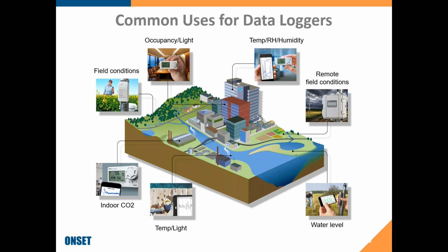Indoor CO2, very prominent data logger. I'll have a short explanation on how these are being used today. You have temperature, relative humidity, and carbon dioxide measurements, which is helping to provide airflow in buildings, which is a very important measurement right now. This uses USB or Bluetooth. So very important data logger right now for the times we're living through.